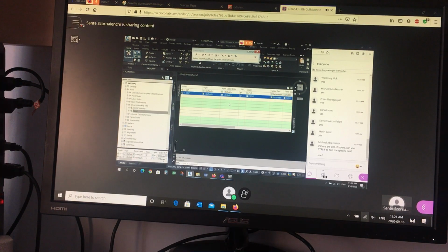If you take the time to do all that programming, spelling counts. If you type it in wrong, remember what I did at the beginning? I put an underscore by mistake. If you put an underscore instead of a dash, it won't recognize that. If you don't program this, any point that doesn't fall into this category by default will go on the current layer. In this case, layer 0. Whatever the current layer is. That's why they were all on one layer. This set of instructions is very useful for taking points of like descriptions and putting them on the same layer.